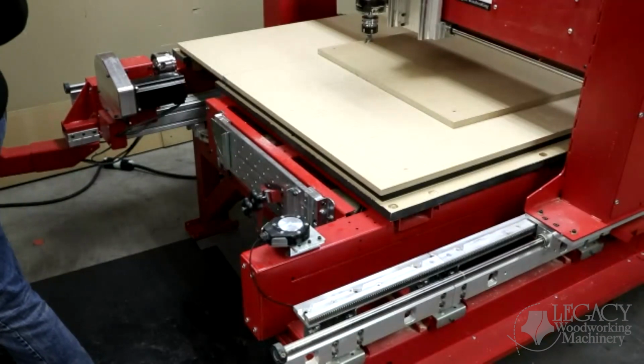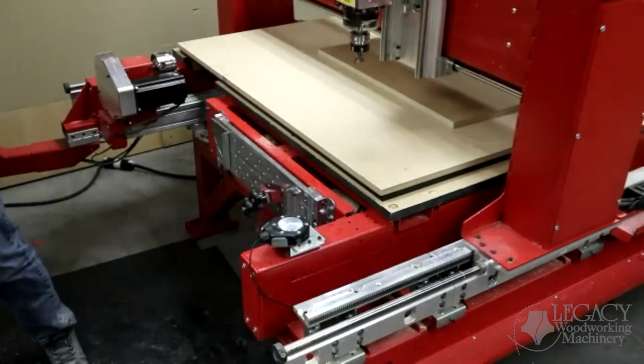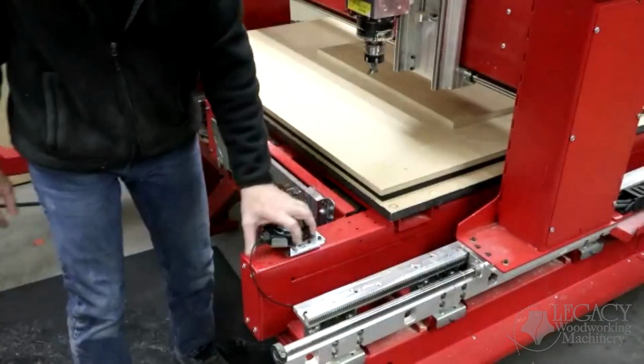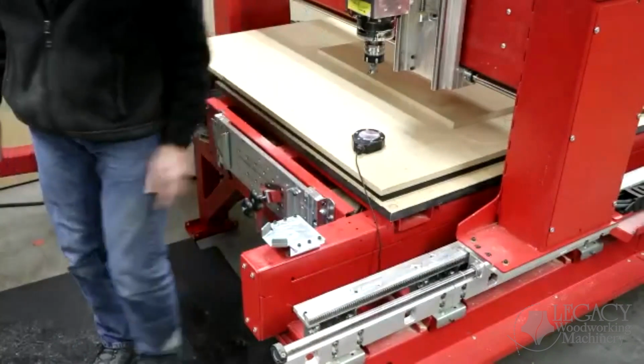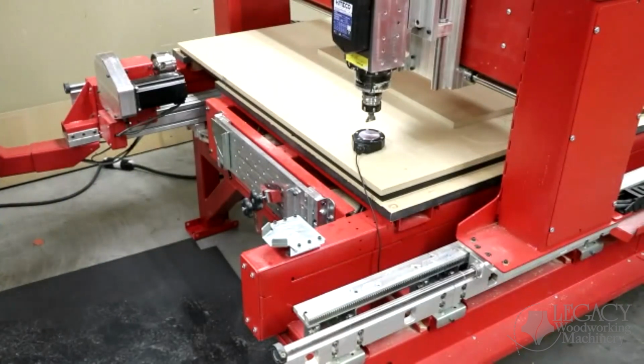Let me just switch over to this program, and maybe you can see this. Let me, real quickly, move this cut over here so you can see it. Okay, so this is how we're going to set up the smart tool. And if we're doing multiple tools, you're going to always start here. And before you hit that setup button for multiple tools, you have to have the router bit positioned over the smart tool pad like this. Now, I'm going to go ahead and just run this so that you can watch it work.